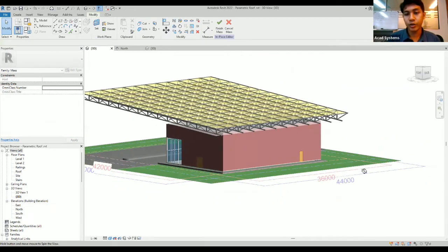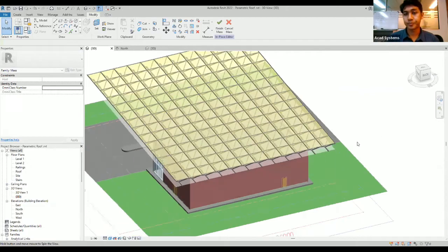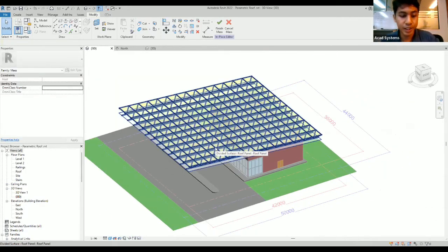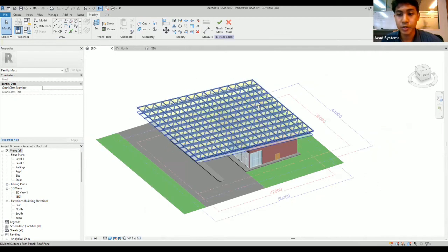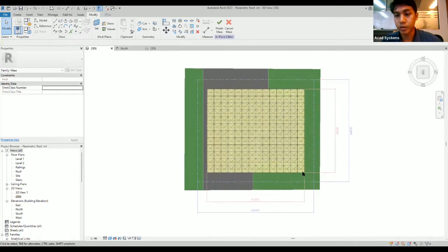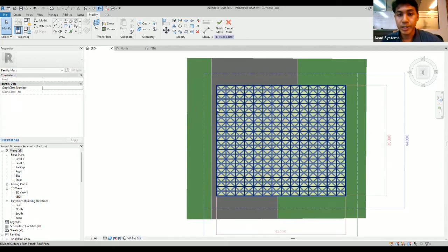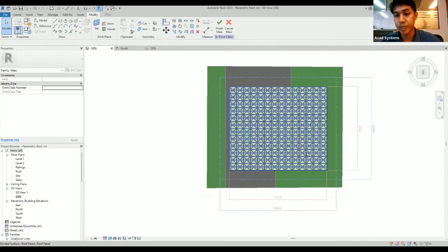And then your roof is basically done. So the thing that I was saying earlier about the parametric, about changing the dimension, and these patterns will just follow through. So if I go to the top view, this is according to the red roof line that I created. So how do I change this easily to this blue line, just to make this roof bigger?